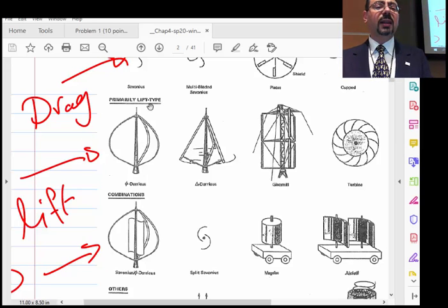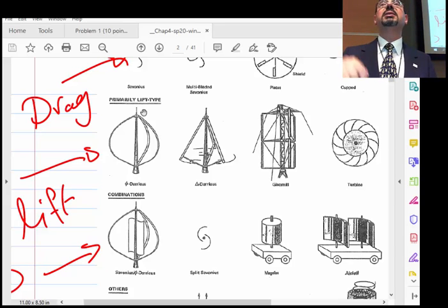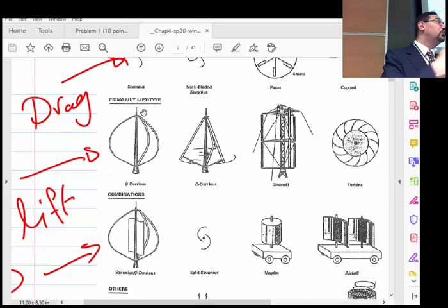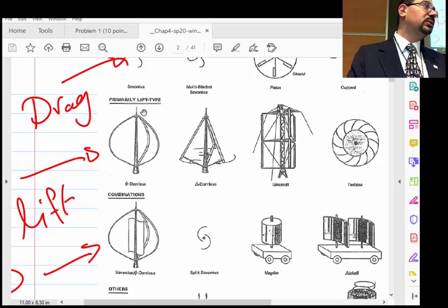But because of the vertical axis, in part of the circle they are moving with the wind, nicely flying, generating lift, but then on the other side, when they are flying against the wind, that's when they start losing force, basically. They lose because they are flying against the wind. So the lift force generated on them, although they are airfoils, is actually not in the right direction. Okay? So it will oppose their motion.